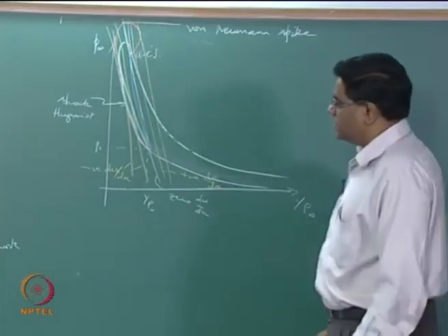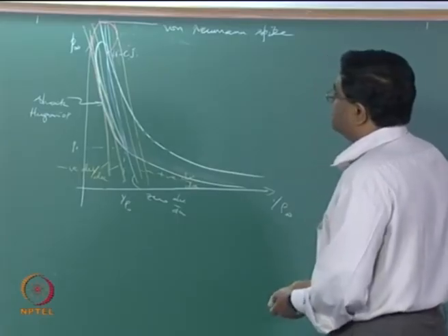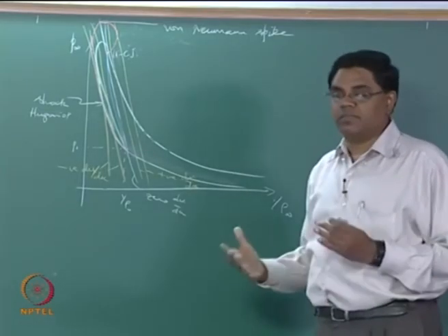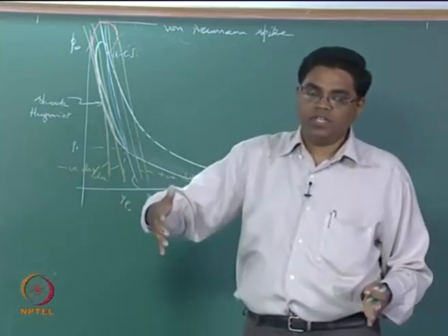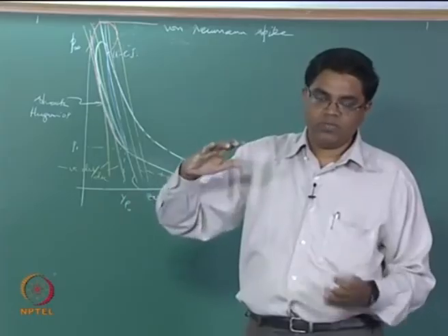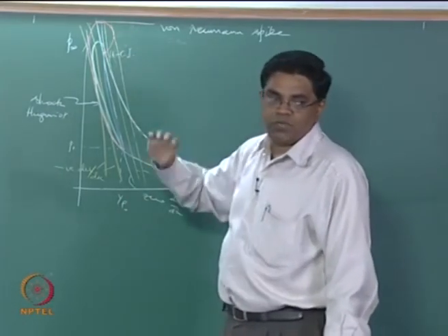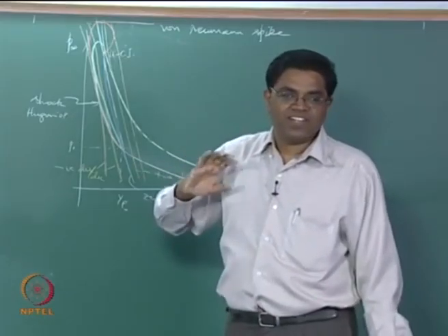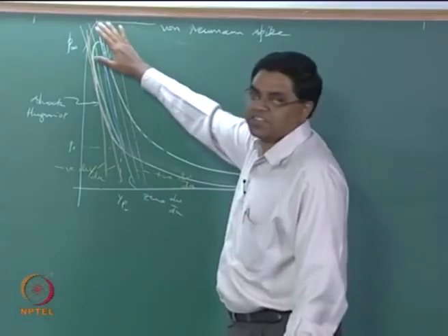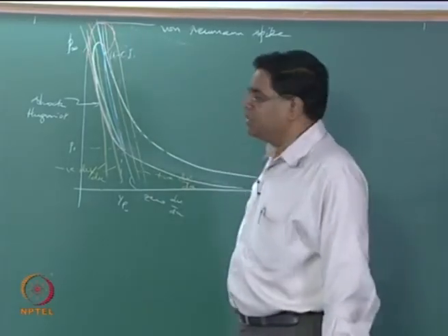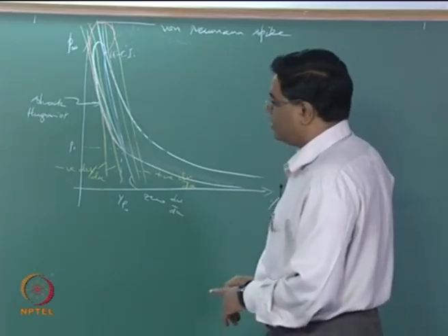Alright. So this is a way by which you can compute the von Neumann spike and get the worst case pressure, or worst case or best case depending upon what your goal is. So if you want to have your detonation wave inside a chamber and you want the chamber to withstand the pressure, this is the worst case pressure. But if you want to cause destruction by pressure by having a very high pressure region, then this is the best case pressure for you. So this is the extreme pressure that you can think about within the framework of the ZND model.